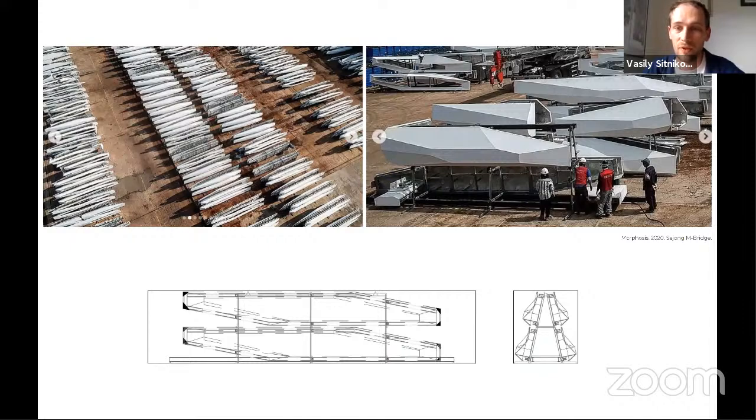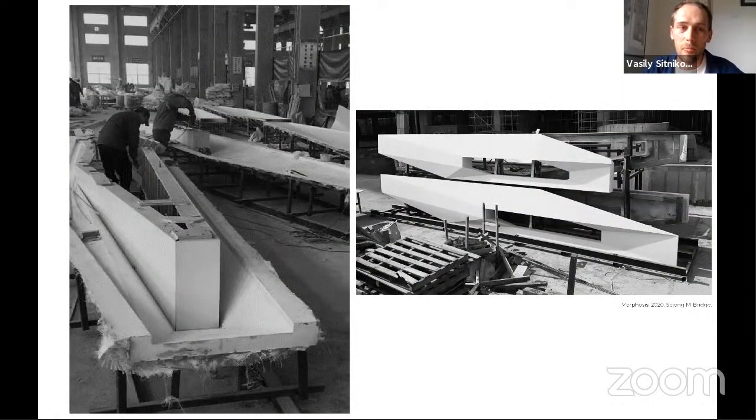construct the project. So there was also another parameter which had to be considered, which is the shipping size of the element. Here you have the diagram of a 12-meter container, which fits 4 of these facade panels at the same time, right? Because they are very thin, they are quite light, and one container could carry 4 of these elements, even though the limit is at about 1 ton. The practical drawbacks, however, are that the formwork needs to be crafted for each element, because sometimes the geometry does not allow reuse of the formwork. So certain constraints stay with it. Still, the fact that it is no longer a solid stone, but just a shell, pushes the performance quite high.